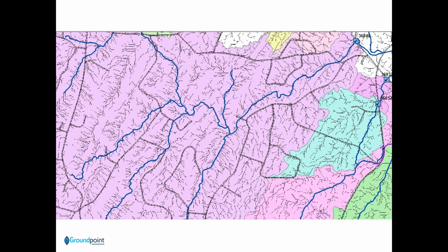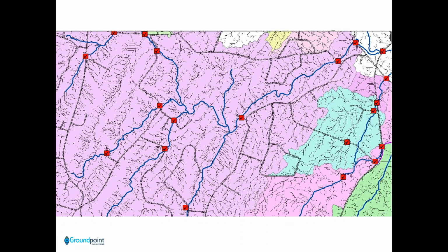And so one of the nice things about this process that I want to point out is that it's scalable. And you can see in the upper right-hand corner, these boxes in blue indicate the county-managed culverts. And so we can map the drainage area associated with those culverts, which is represented here in pink and in green. But if we're interested in higher resolution, we can actually put in all the town culverts that exist inside those larger drainage areas.